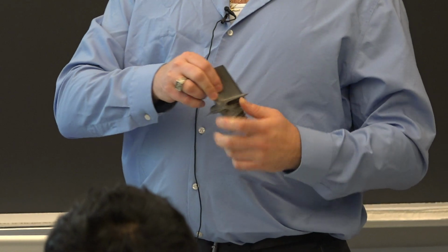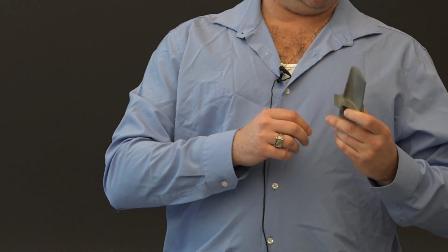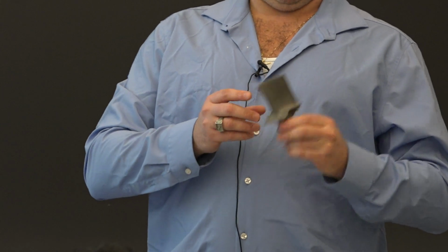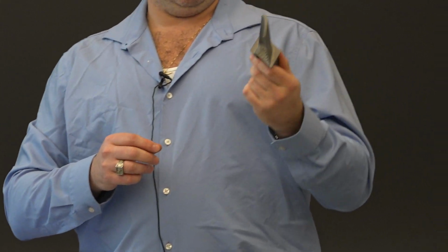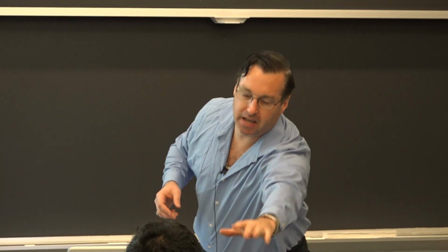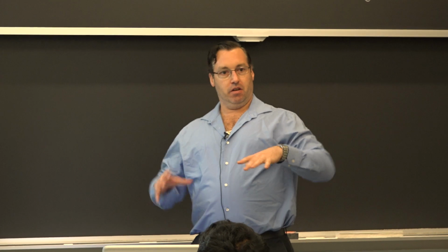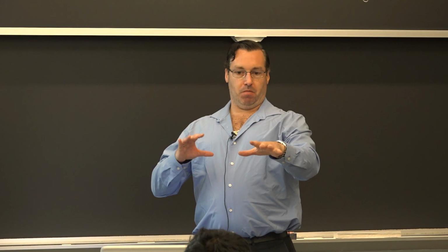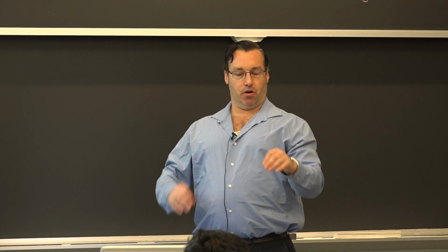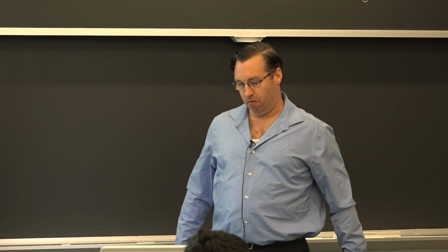And if these cooling channels aren't here, for the turbine section, at least in the airplane engine, the plane operates beyond the melting point. This should be an Inconel or typically a nickel-based superalloy. The notation on that blade deals with the inspection, where they found some anomaly during the repair. So that's just the writing from the inspector to remove that from service.